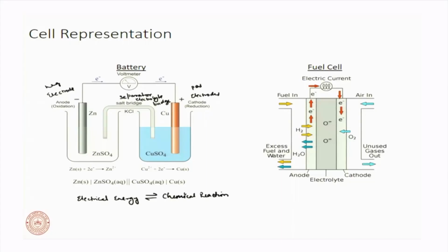Therefore, we can see that the battery itself is a multiphysics problem. We are concerned with charge conservation, mass conservation. At the same time, we are also concerned with Ohm's law or a current voltage relationship. So, we are now gradually moving away from single physics and starting to enter the domain of multiphysics systems. Okay.